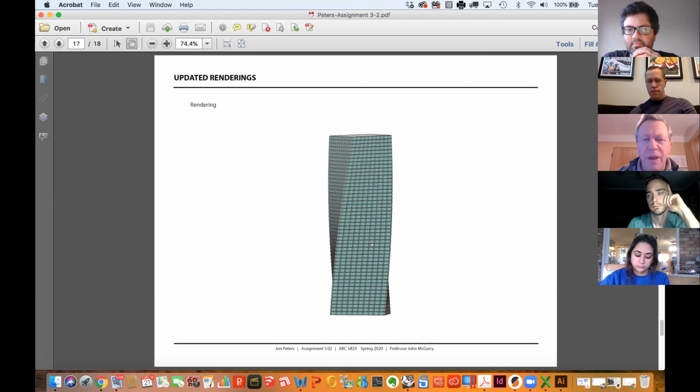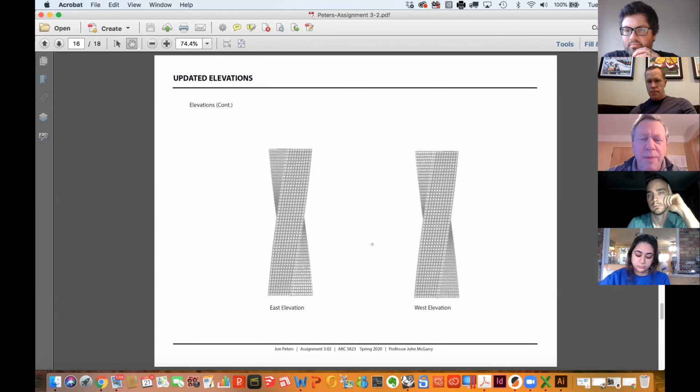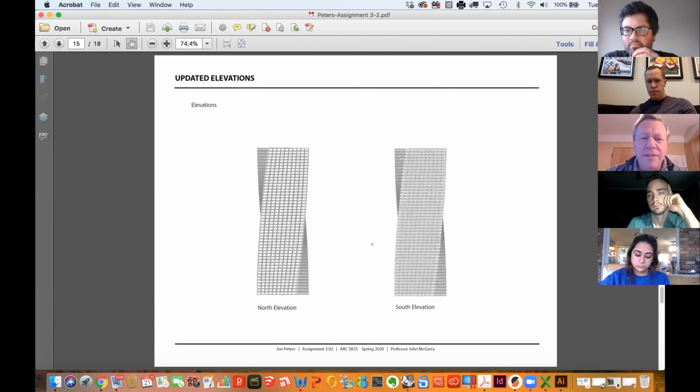Further, I'm concerned too, your assumption about the south may not be entirely correct, in the sense that really when you're talking about shading on the south, you want overhang shading because the sun is above.